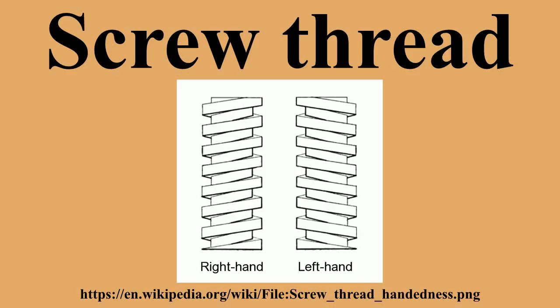The seal provided by a threaded pipe joint is created when a tapered externally threaded end is tightened into an end with internal threads. Normally a good seal requires the application of a separate sealant in the joint, such as thread seal tape, or a liquid or paste pipe sealant such as pipe dope. However, some threaded pipe joints do not require a separate sealant.